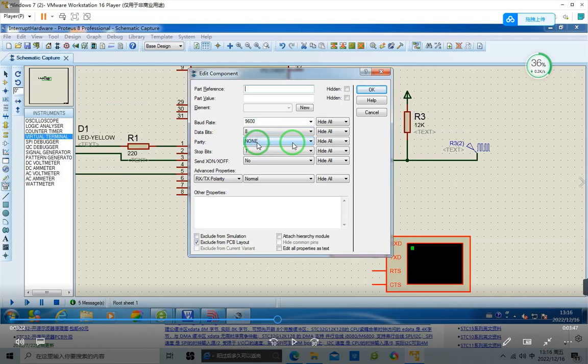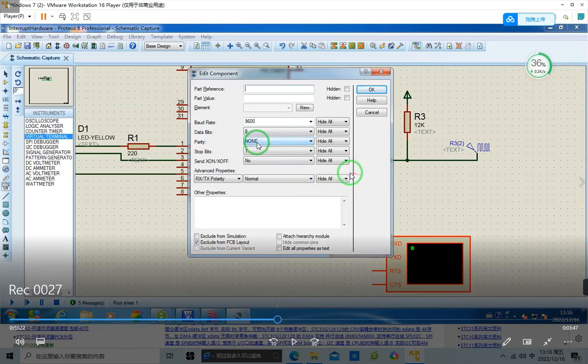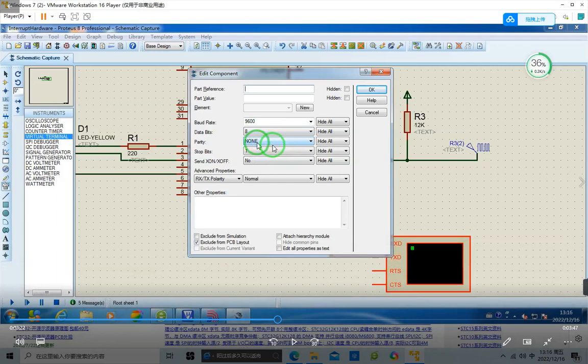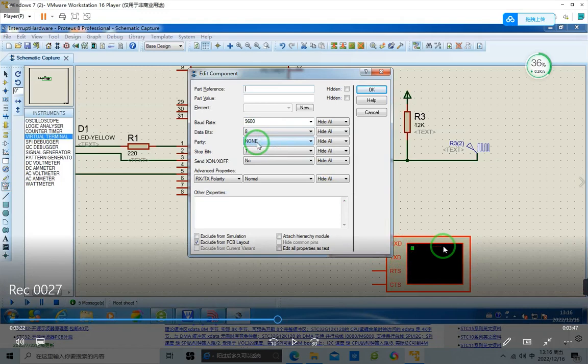You can select none even in industrial, but you need to add CRC checksum by yourself. Even if you select odd or even parity, there's still some possibility it will generate error, but not detected by the other side.